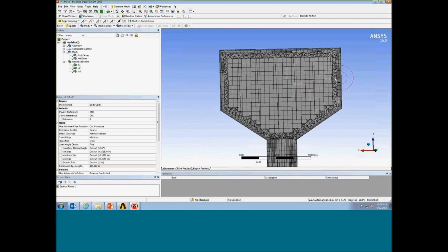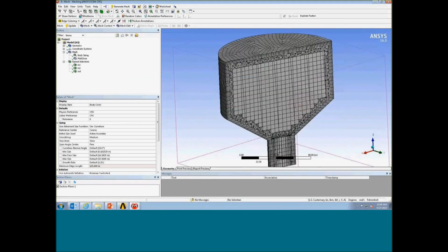Between the boundary and the hex core, where the program failed the first try because it could not place all hex elements, this time those regions are filled in with a layer of tetrahedra. So overall, the mesh is pretty good, and it offers the advantage of most of the hex elements in this tank with just a small portion of tetrahedron elements.